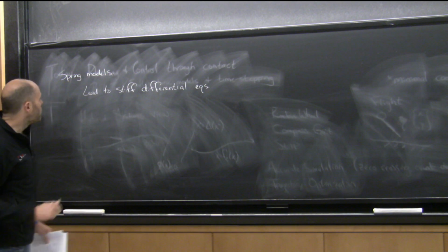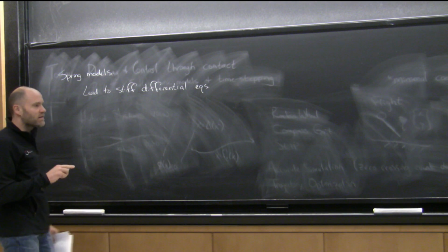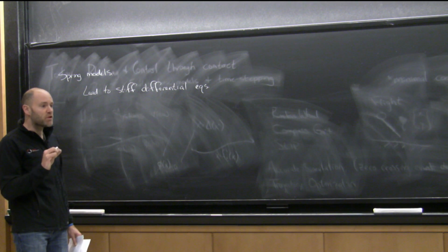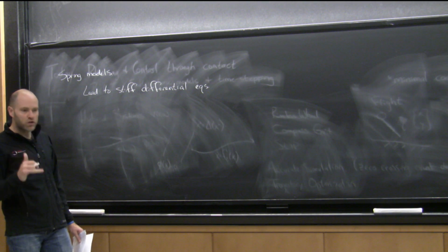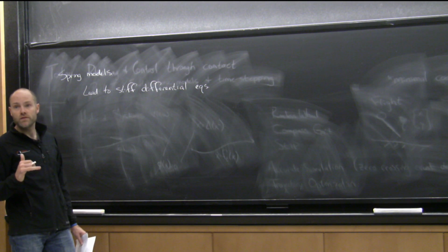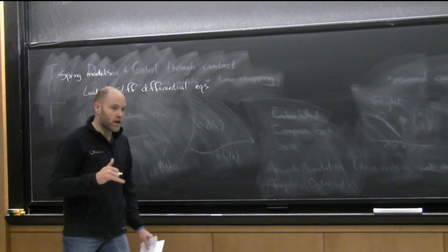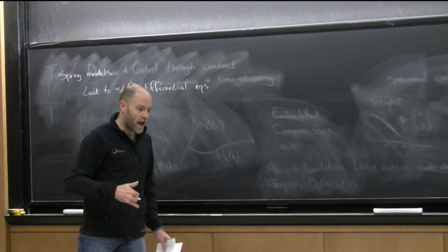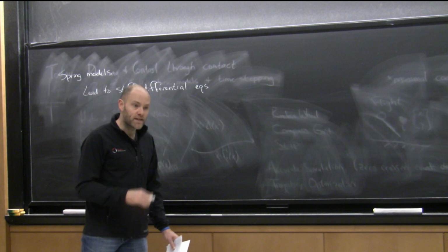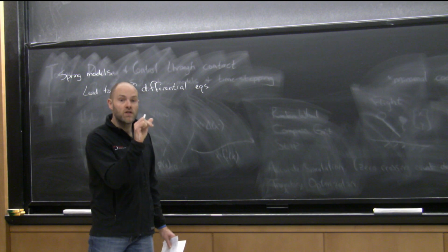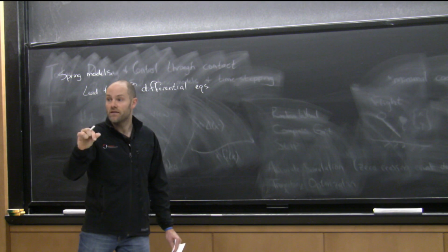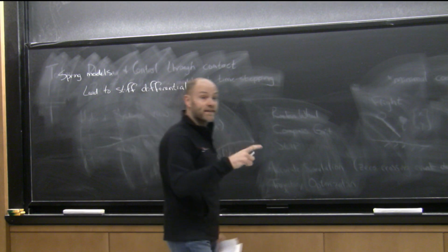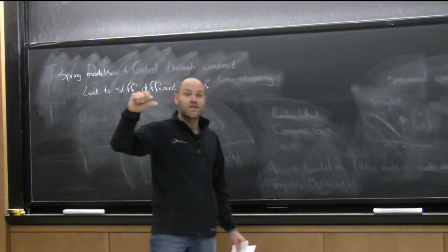Okay, so why is that painful for our optimization tools? I mean, for simulation, there's good tools for solving stiff differential equations. You could have a variable step integration that's even monitoring your accuracy. When it comes into contact, it will automatically schedule smaller time steps to be taken as the simulator proceeds. And then as it comes out of contact, it could then increase the time step of the simulation and be efficient again.